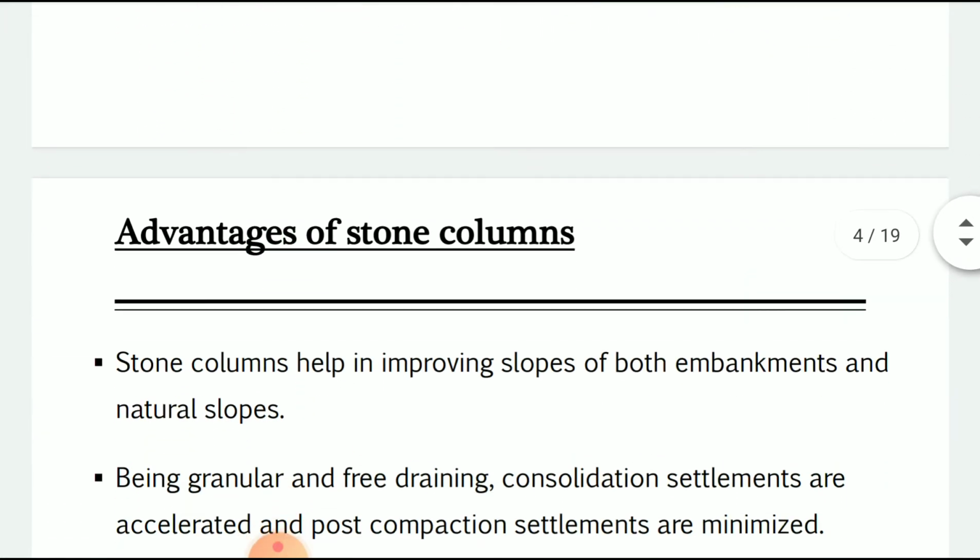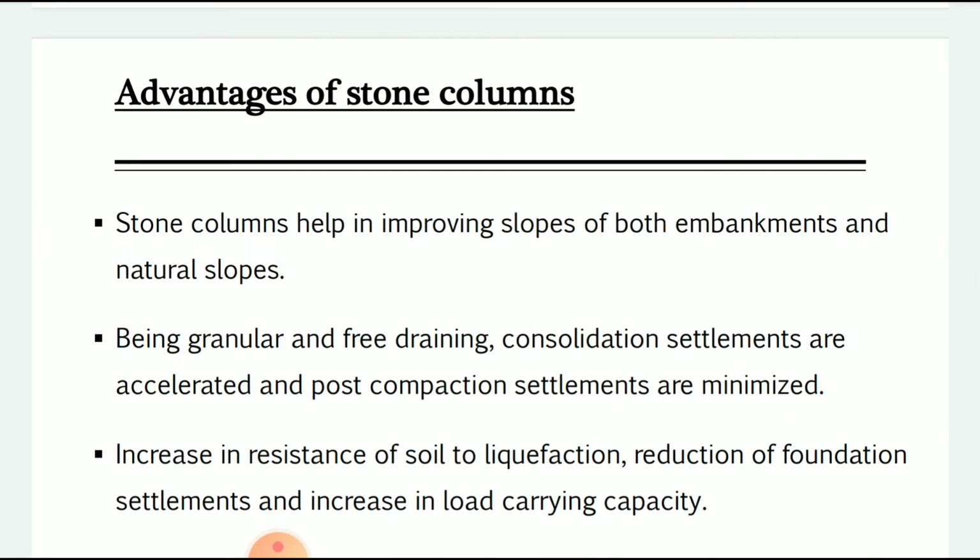Next are the advantages of the stone column. Firstly, the stone column helps in improving the slope of both embankments and natural slopes. If embankments are present, the stone columns improve both types of embankment and the natural slope present on the ground.